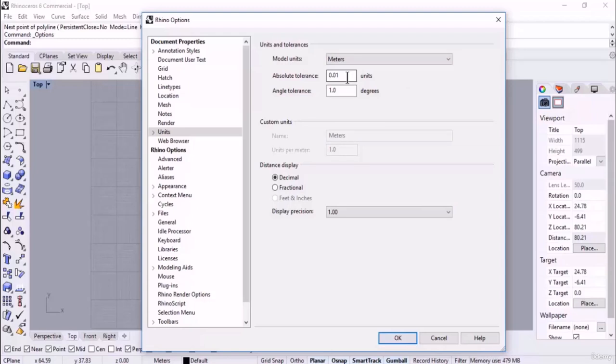So here, as you can see, the lower fractional parts of the value are considered by the tolerance, like 1 meter and 23 centimeters. However, we can maximize the value of tolerance by adding another 0.001, and this is better and the recommended absolute tolerance. And then for the angle tolerance, for example, if you are working with less than 1 degrees, you can specify 0.5 as the angle tolerance per degrees. However, we usually specify 1 degrees for the angle tolerance, and it is enough.